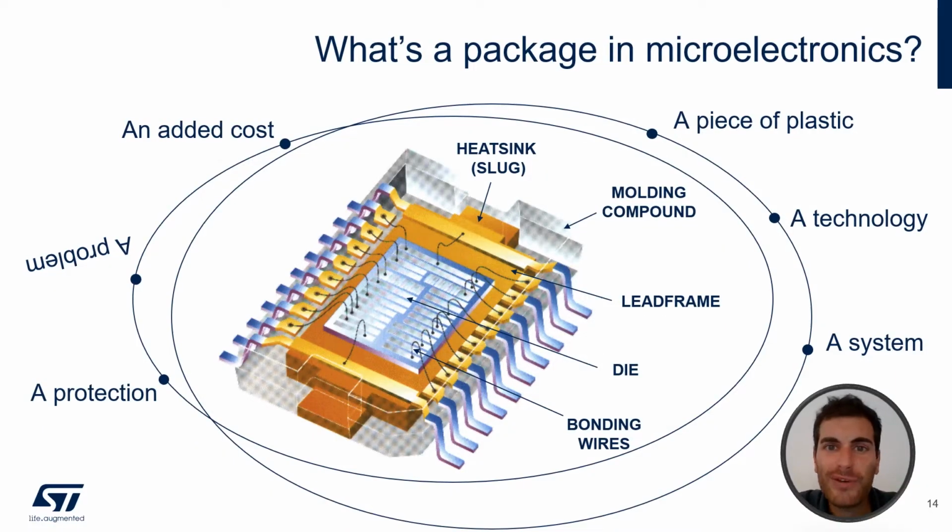So, after the description of my company and the R&D team, let's start to introduce you to the concept of IC packaging in Microchip. IC packaging is the final stage of semiconductor device fabrication. The device, the die here, is laid on a metallic lead frame and it is encapsulated in a supporting case made of molding compound, which prevents physical damage and corrosion.